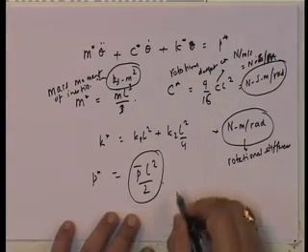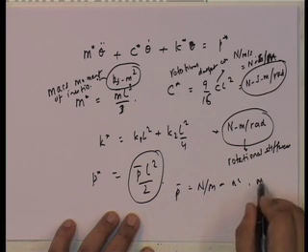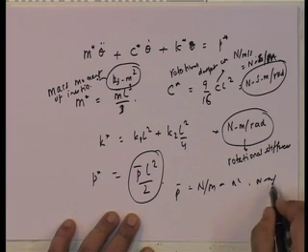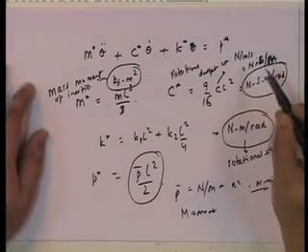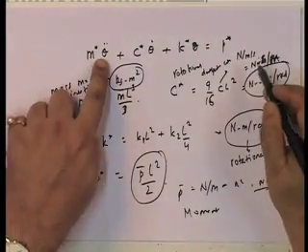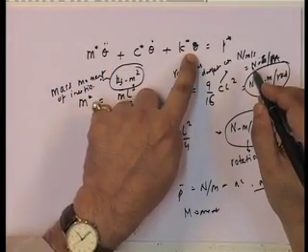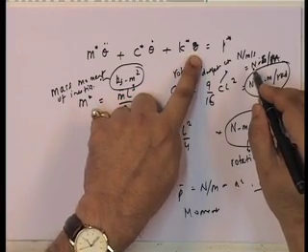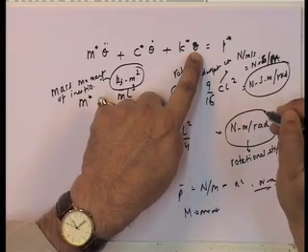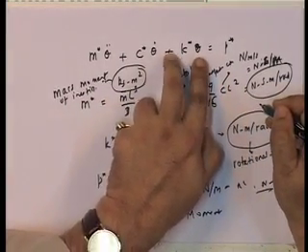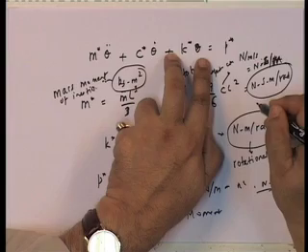And let us look at this load. What is this load? P bar is Newton per meter into meter squared is Newton meter. Well, this is again Newton meter. What is Newton meter? Moment. Let us look at this equation. What should this equation look like? Angular acceleration, angular velocity, angular displacement. Rotational stiffness into angular displacement is the spring moment.